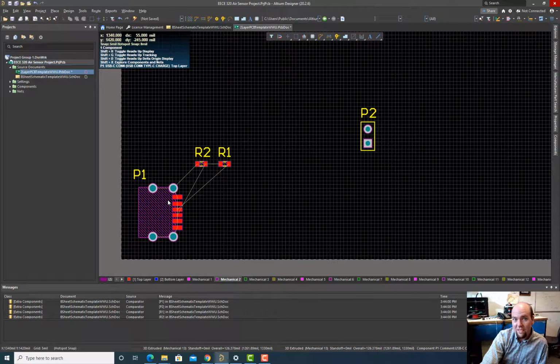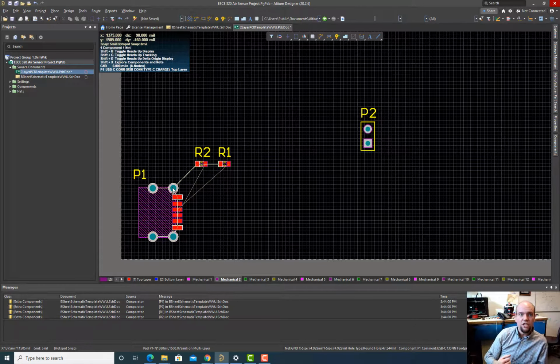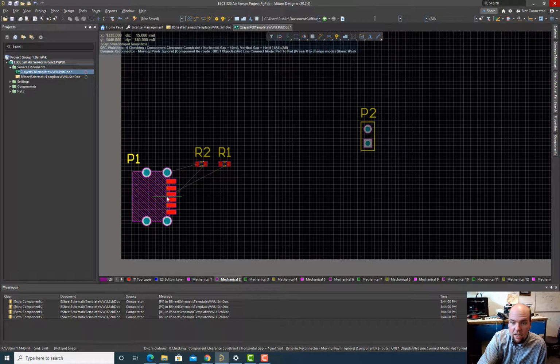The thing with USB is it's about an electrical connection, but it's also about a physical connection. The through-hole connection for USB gives a nice, rigid, physical connection of the connector to the board so that we don't rip it off. A lot of you have probably broken electronics by ripping USB connectors off. For a while, there were a lot of micro USB connectors that were surface mount only, and those don't tend to last too long. So they found with USB, it's good to have through-hole connections, a nice, solid solder connection of the actual connector to the board, and that's what's going on here.